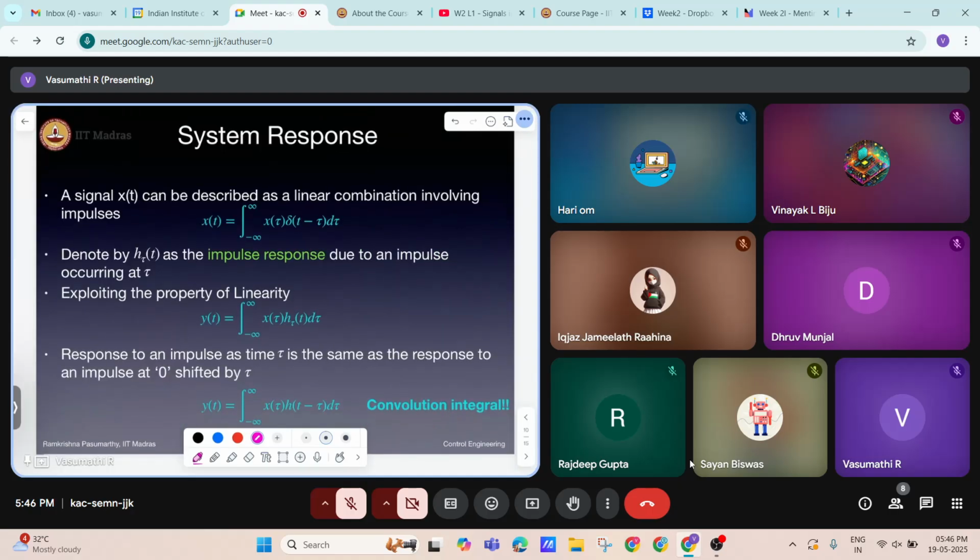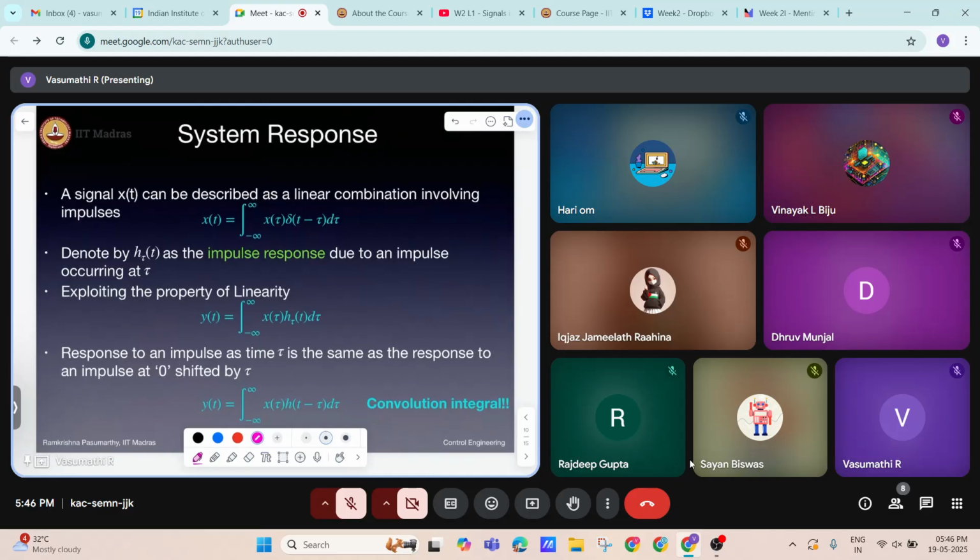And then, what is an impulse response? This is where the convolution comes into action. Convolution basically represents how an input signal is modified by any system. If I have a system, I am giving one input and I am getting an output. So this convolution represents how the system is modifying this input signal to get the particular output. That's what the convolution represents.